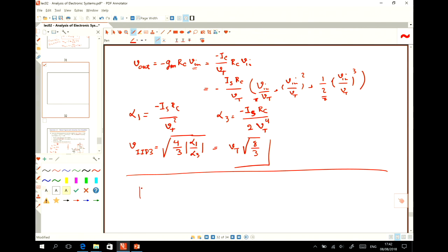So we have an amplifier, and the output of the amplifier is 0 dBm, and here we have a 50 ohm resistor. What is the peak-to-peak voltage at this point? First of all, what is the meaning of 0 dBm? 1 milliwatt, yes, not watt. So the power that we have is 1 milliwatt.